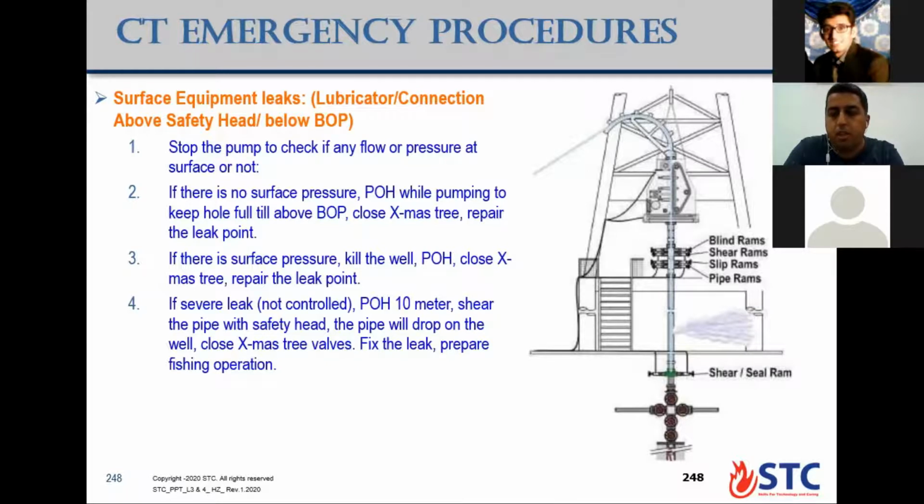So bullheading will be the good option, because if we wait for 30 minutes and in those 30 minutes the lubricator keeps on leaking, that is dangerous. Okay, no problem. You pump, you bullhead from the kill line down. So if it is fast for you, it is a good choice. No problem.